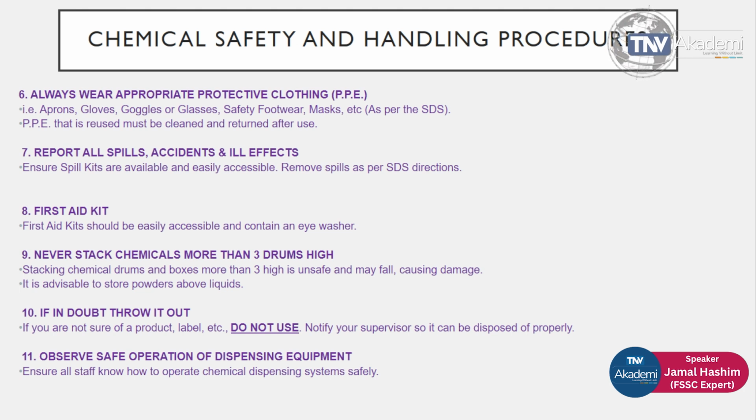Never stack chemicals more than 3 drums high. Stacking chemical drums and boxes more than 3 high is unsafe and they may fall, causing damage. It is advisable to store powders above liquids. If in doubt, throw it out. If you are not sure about the product, label, etc., do not use it. Notify your supervisor so it can be disposed of properly.